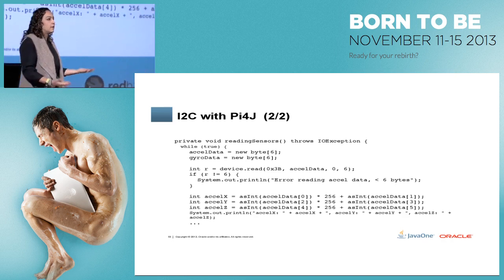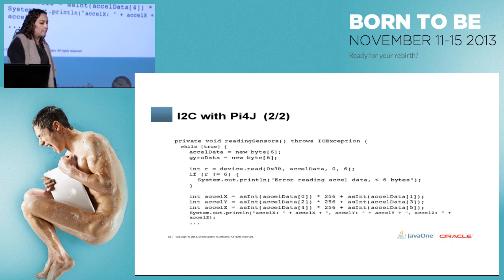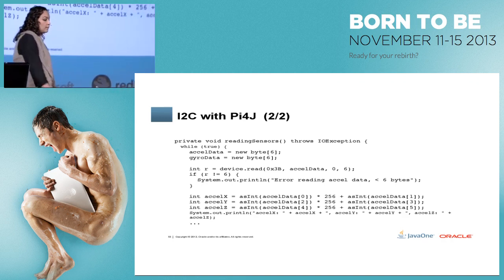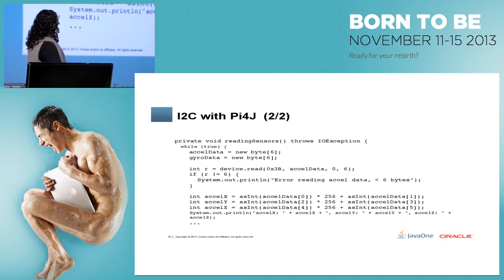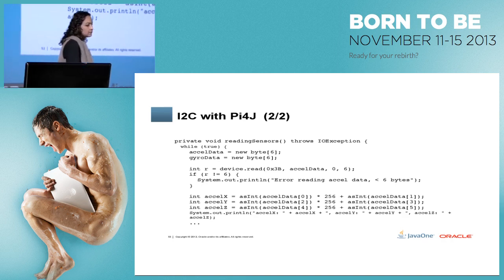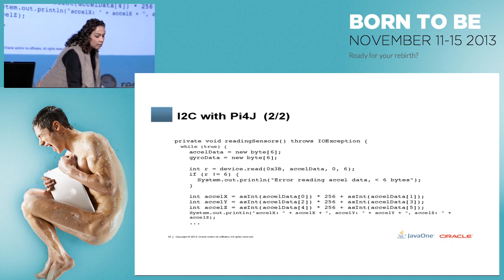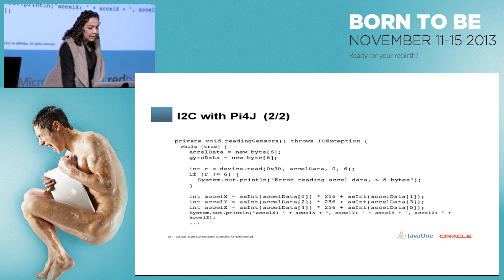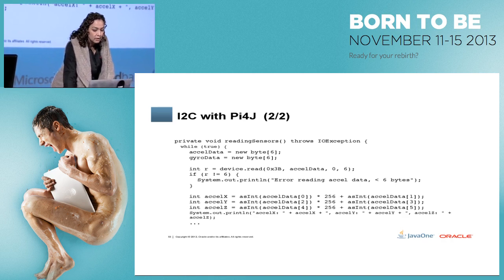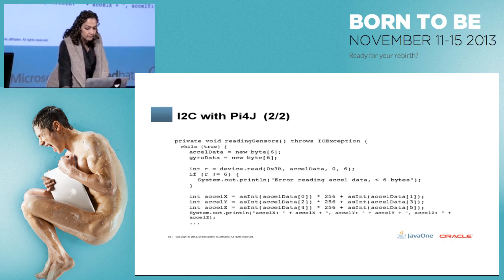And again, each of them is using 2 bytes, so we have a 16 bit reading for each sensing information. So that's what we do in the pieces here, acceleration X, Y, and Z: concatenate the 2 bytes that you need to read for each axis.